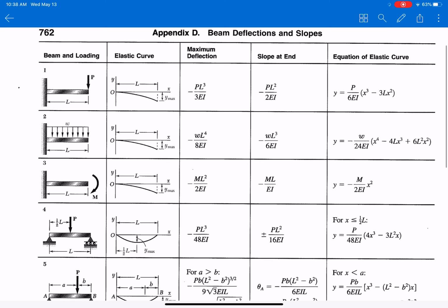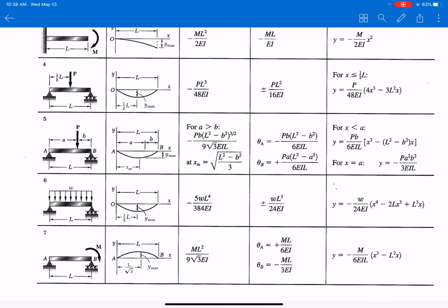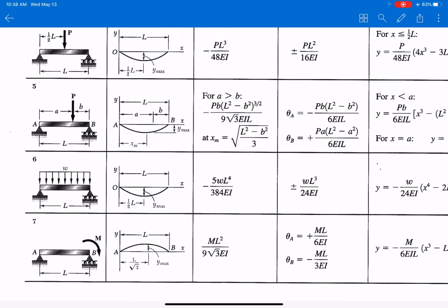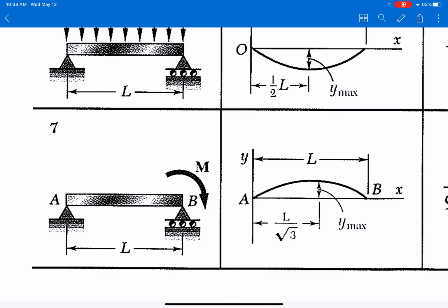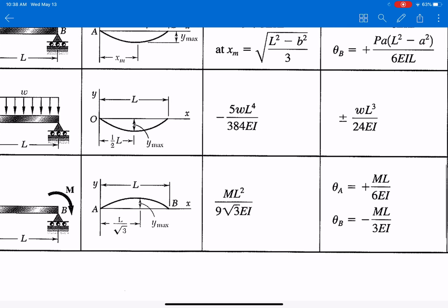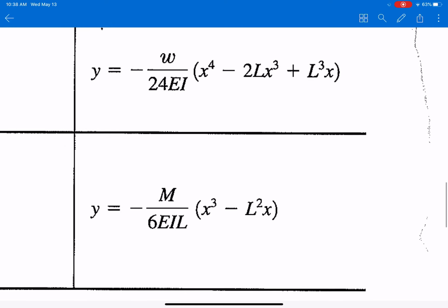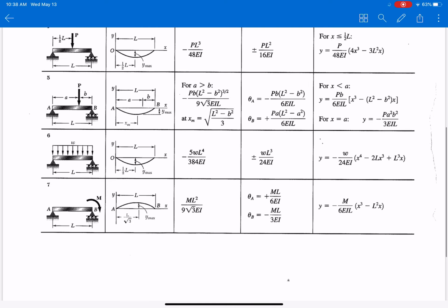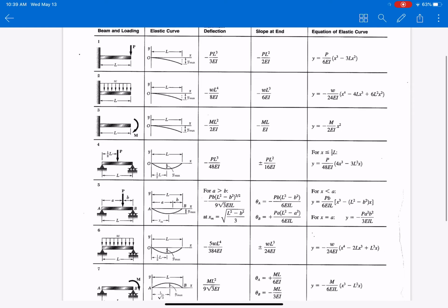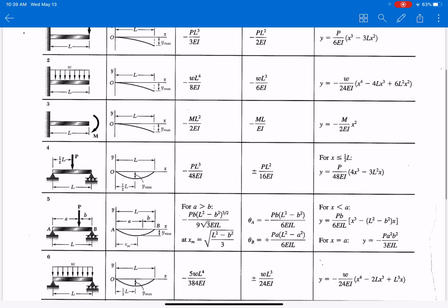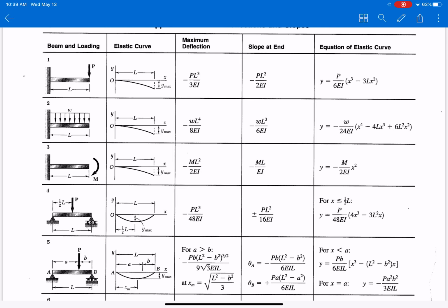As you can see, we did the problem in worksheet 15a, and you can find the elastic curve function with multiple integrals and then end conditions to determine that equation. But basically the equation is similar to figure 7 in worksheet 15a, and the integrals take a long time to solve. For each support condition and load, the table gives us the equation for elastic curve, slope, etc. So we can just use the table.